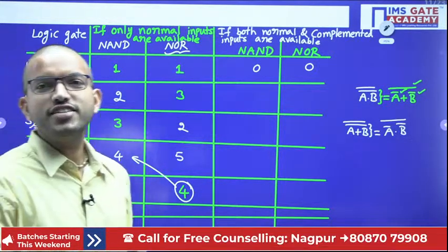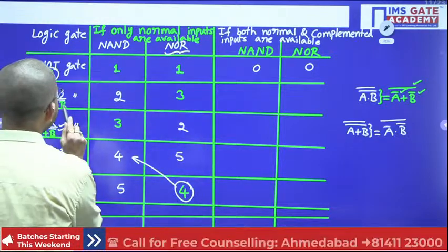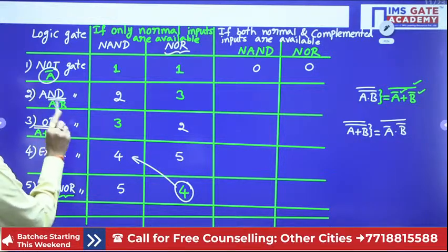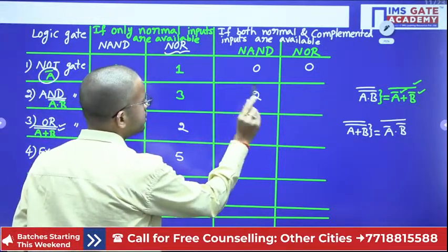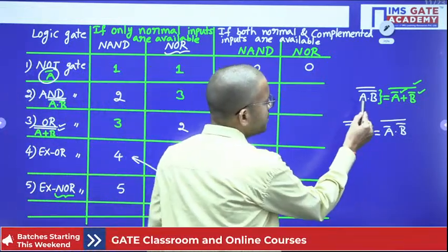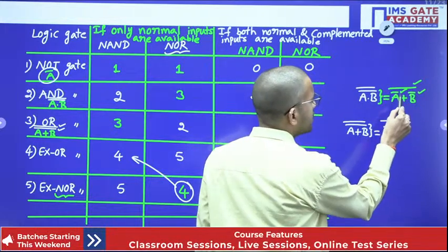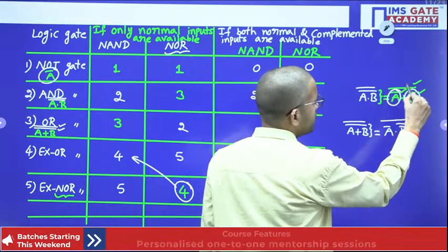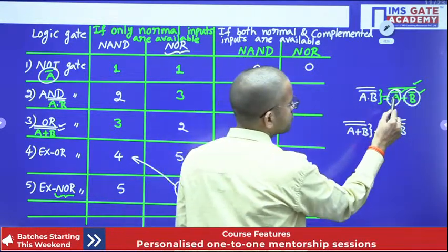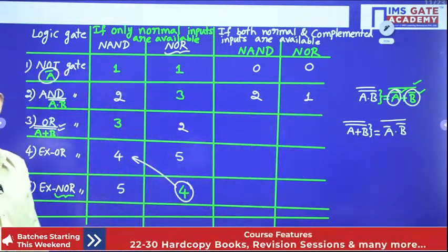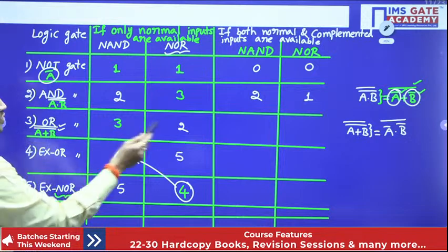Yes, very good, Ravi, very good. So here for the AND gate, earlier we have written (A B bar) whole bar, right? So anyway there is no change in terms of NAND gates, 2 only. But for NOR gates, if you observe, (A bar plus B bar) whole bar, A bar is already available, B bar is also available. So that means we require only one external NOR gate. A bar and B bar we will pass through one NOR gate. So that's why here it is 1. Right, very good. With the same understanding, you can easily answer here also regarding the OR gate.